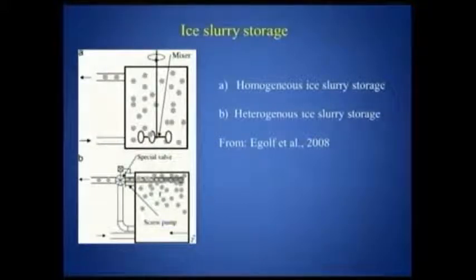So you can always separate them again. In this method that was proposed by me, you can, by a screw pump, take high concentration ice slurry out of the tank, mix it with water from the bottom to your right concentration, and go out with the predefined ice concentration. By this you can save the mixing energy, which is a substantial energy in ice slurry technology.